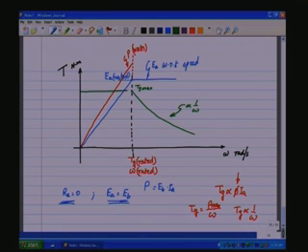But in the region below rated speed, you could achieve a constant torque up to the maximum. There is possibility of obtaining a constant torque here, because the speed is less than the rated, and as the speed is less than the rated, IA can take a lesser value, and therefore, for any load one could achieve a constant operating point below the rated. But beyond the rated there is an upper limit for the torque, which will have a proportionality of 1 by omega. So, this would be the achievable maximum torque curve, the green line as I am showing here, with respect to omega.